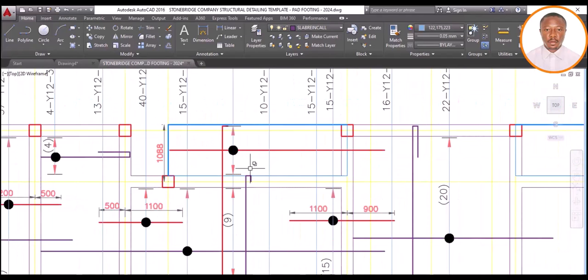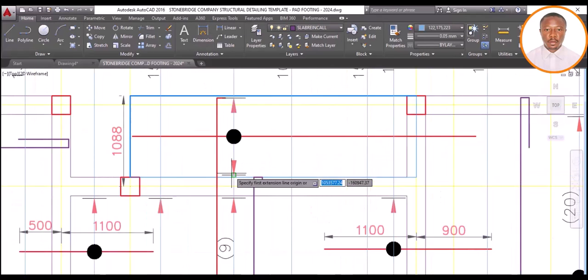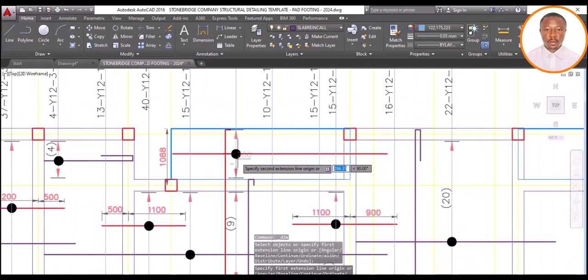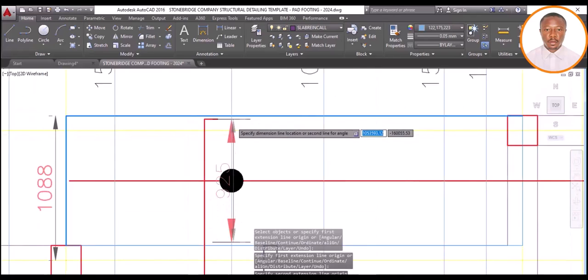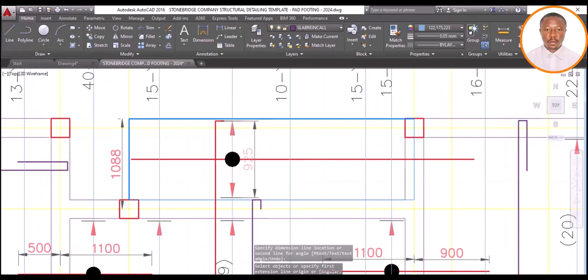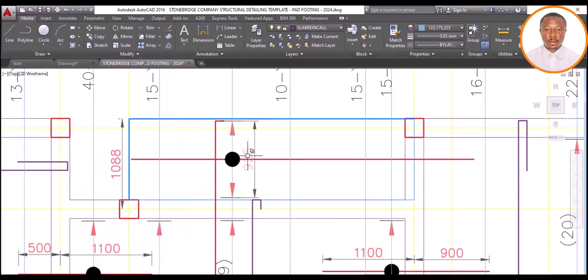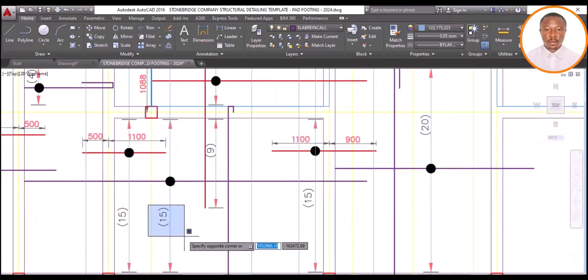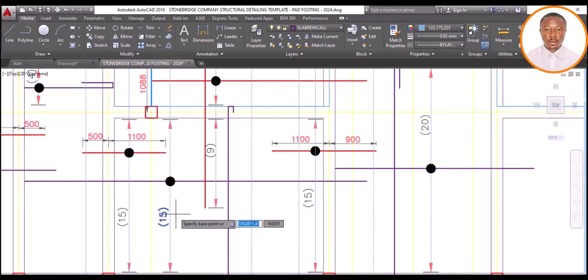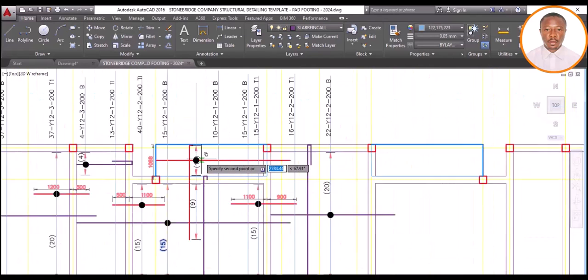So also come here. How many do we have? So pick my dimension and come to this place and put, we have what? 925. So carry my dimension. 925 divided by 200. So it's what? It's 4. That's a 5. That's 5. It's advisable that you should always add 1. So that's 5. So I carry my number. I copy my number. I come here, copy it, and come here and paste it.